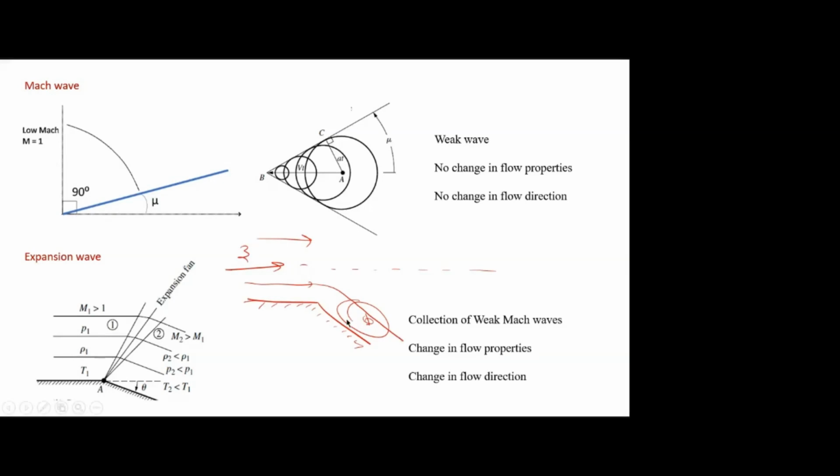Okay, actually the Mach number 3 flow, for example, should go straight, but because of this void, there is a low pressure region, so that sucks the upper flow, so that it is deflected and gets accelerated because of the suction. That's why we are getting an increase in Mach number behind the waves.